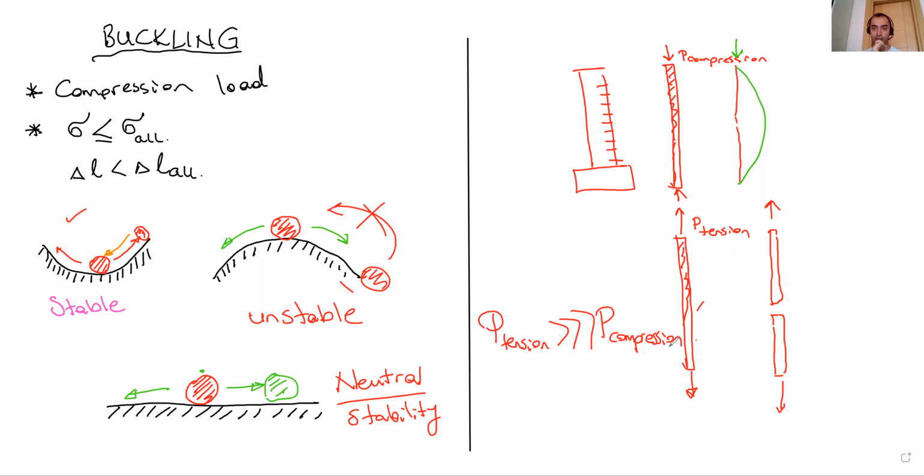Under compression, as you can see here, we change our balanced position. It is going to get a curved shape like the green arch here. When its shape is changed, we know that the capacity of the member changes and gets reduced.